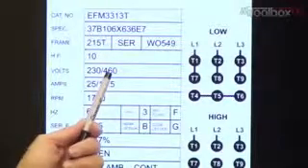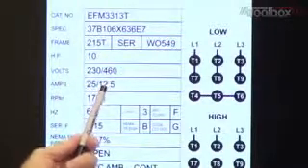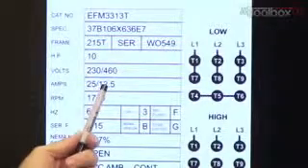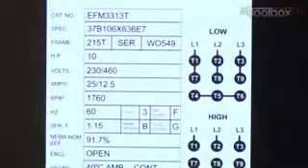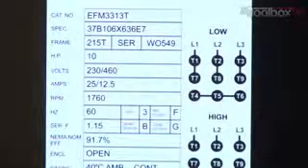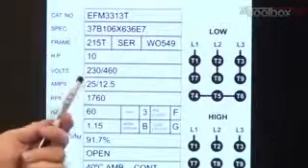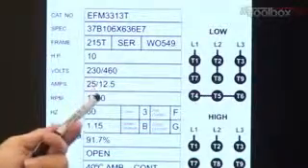You can see if you increase the voltage, the current cuts in half. That's because the horsepower stays the same. There's 746 watts of electrical power consumed per horsepower, and that stays the same, by the way we connect the motor.